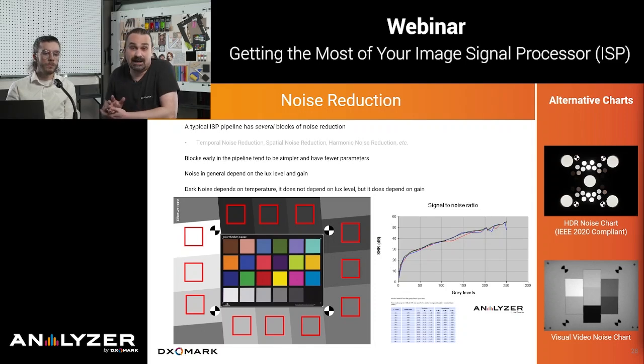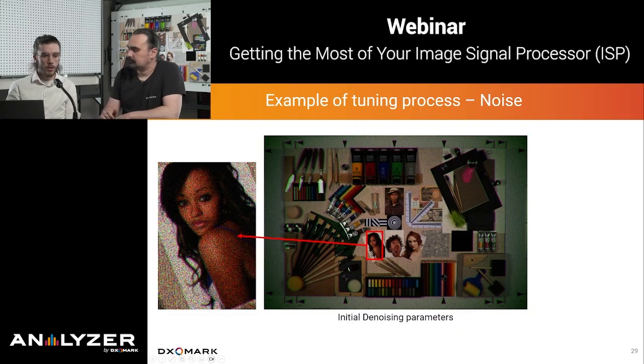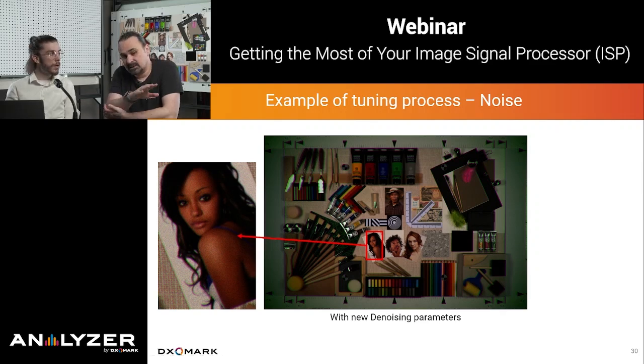That's why I chose the 20 lux. It's a more challenging condition. Let's say I get something acceptable with my sensor. We applied denoising, right? It's a lot better. You notice that it's not completely flat. There is still noise, okay? But the appearance of noise is compatible with what we would have with an analog print, for instance. And if you look at the big image, you don't actually notice it anymore. So we are, at least for the moment, satisfied with this result. It's acceptable, right?